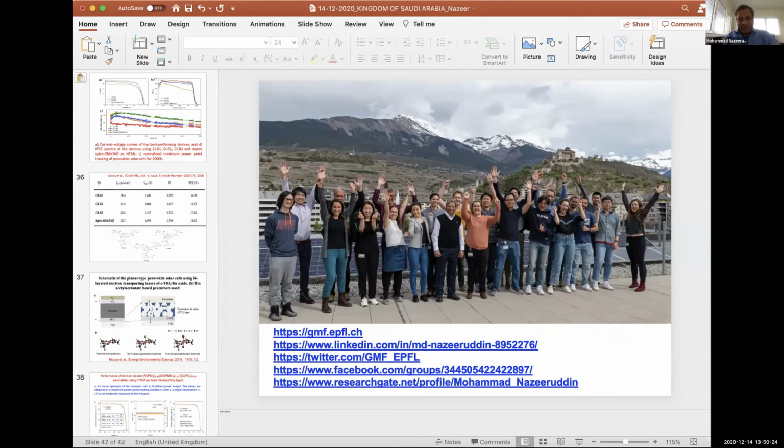Yes, he pointed out correctly. The three-dimensional perovskite is just like a salt. It takes in water because of hygroscopicity. It has a lot of disadvantages. So what we are doing is covering the perovskite with a very thin blanket layer of two-dimensional perovskite, which creates the functionality of hydrophobicity. So that's the advantage of having the two-dimensional perovskite. It covers the three-dimensional perovskite, making it more stable.